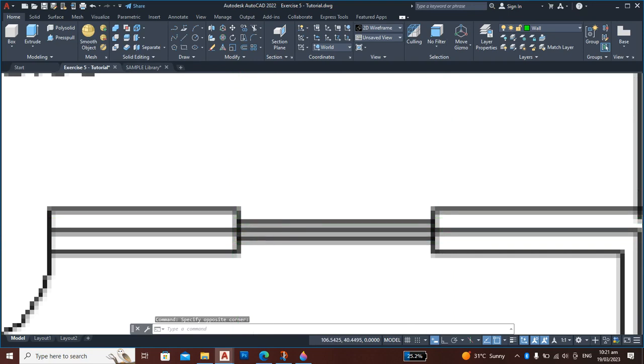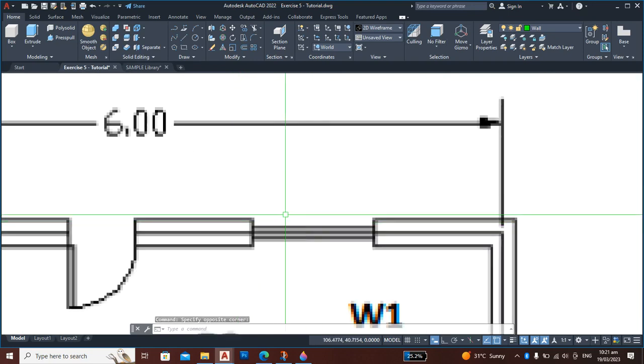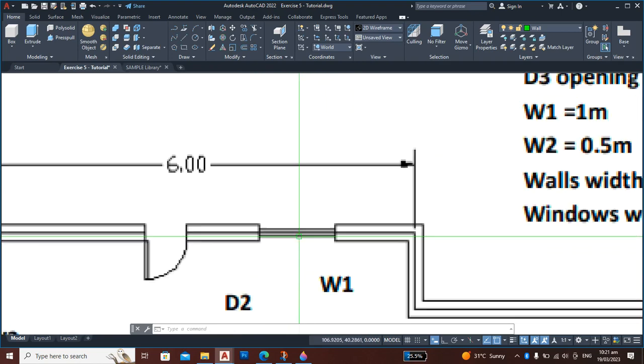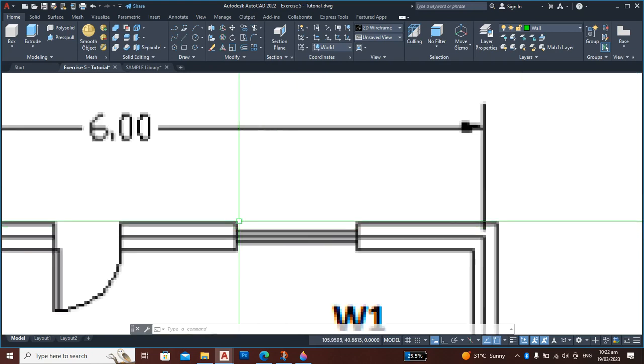But in the example drawing, there should be a line here, not just the width of the window, because there should be a window sill here, the part of that wall where the window will rest. So this is lacking in lines or is a wrong presentation.